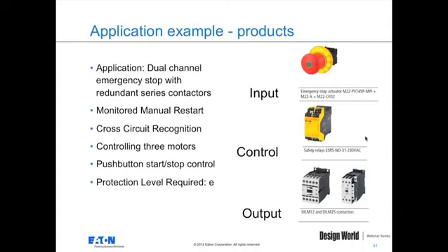We're going to control three different motors, and we'll show that in the power diagram, which is some simple push-button start-stop control. We determined based on the hazards of the machine that we need to design to a protection level of E.